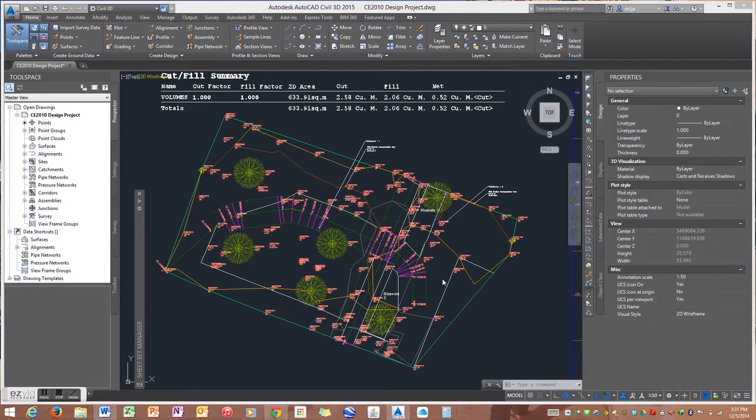First, there are three project goals. One, to increase pedestrian traffic area by 15%. Two, to provide an ADA compliant pathway from the top of the hill down to the bottom. And three, to improve stormwater management. So I first approached the pedestrian traffic areas, and since they were existing, wanted to expand them first and then design the rest of the solutions around that.